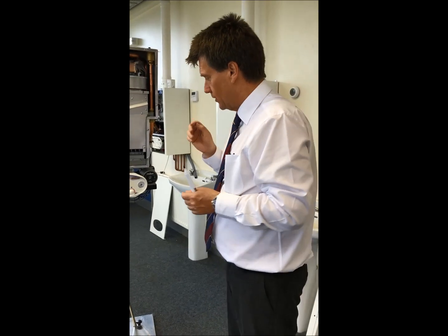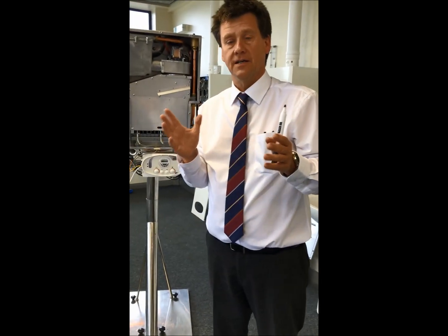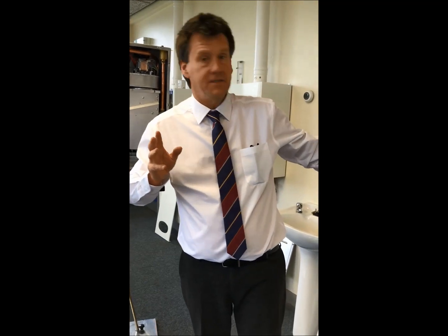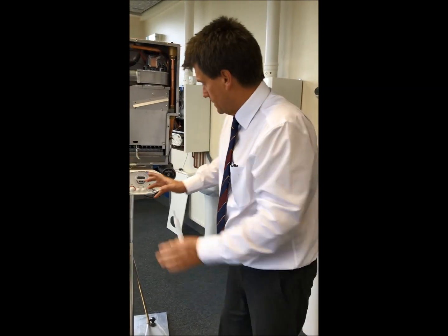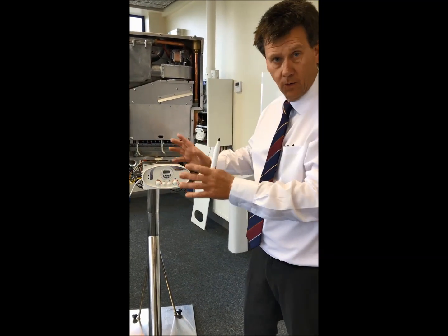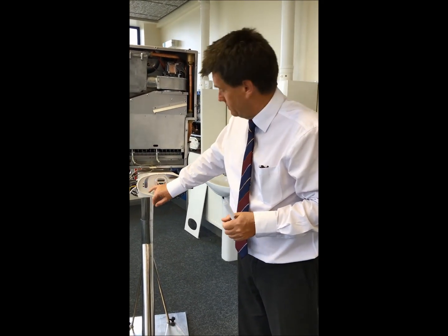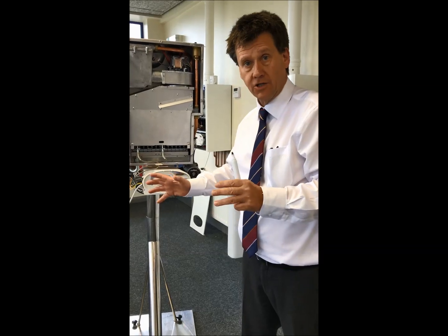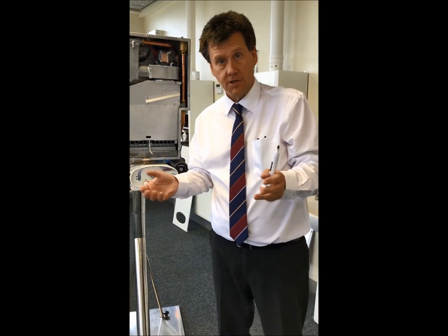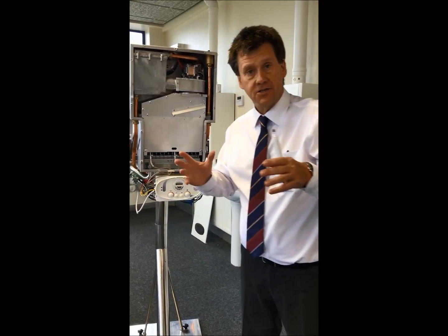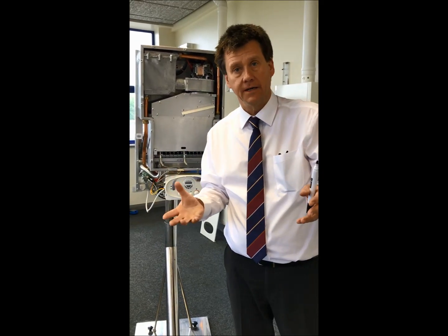But one of the things that we need to understand is sequence. So this has got 28 fault finding codes. This one, the old atmospheric, and they're all the same. The top light depicts power, and the bottom light, when flashing, it's going to overheat for some reason. And if the bottom light stays solid, then it's gone to flame failure.